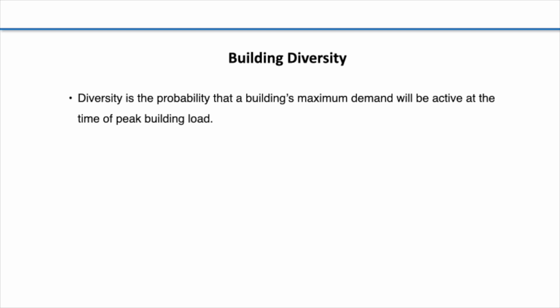One of the mistakes that I see often is that people will use this connection ratio and automatically think that this outdoor unit can now magically do over 100% of its nominal rated capacity, which is not true. So let's now define diversity or building diversity.